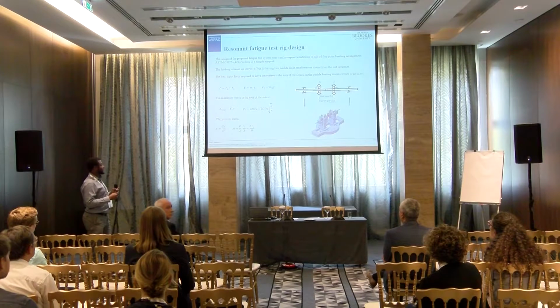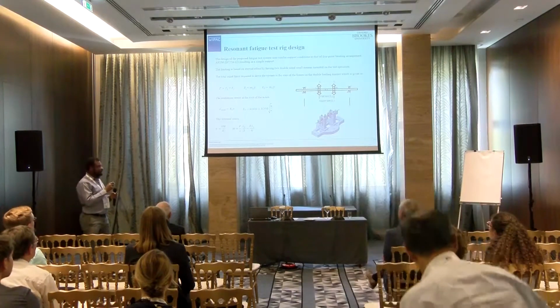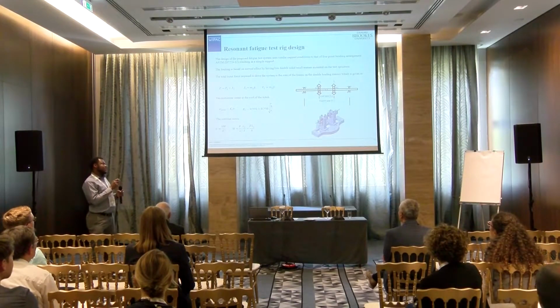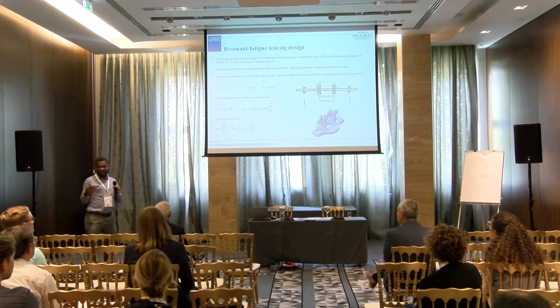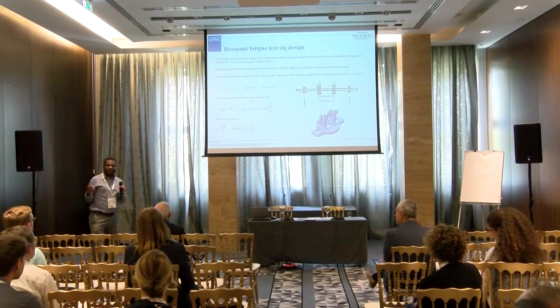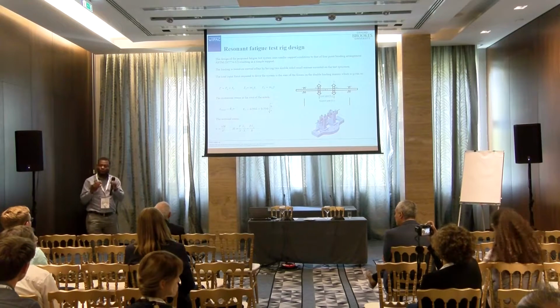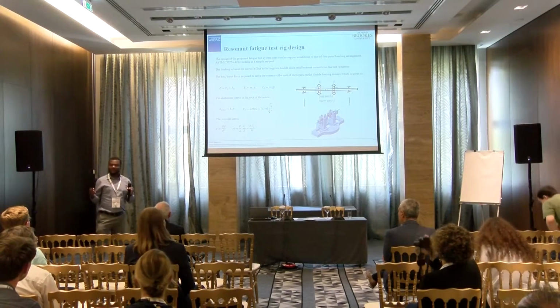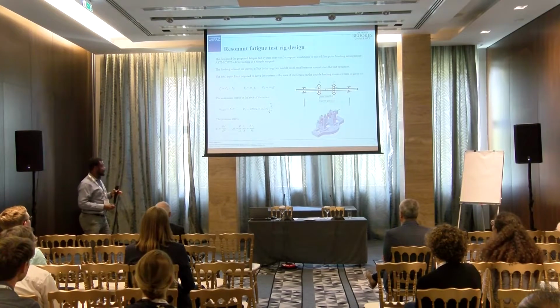The maximum stress at the root of the notch. The notch is very, very critical in this work. It makes it fail where you want it to fail. It's very, very good to have a notch, so you know that there is no issue of stress concentration. So you know you are getting the pure material properties. And that's why the notch is very, very important to use in this work.